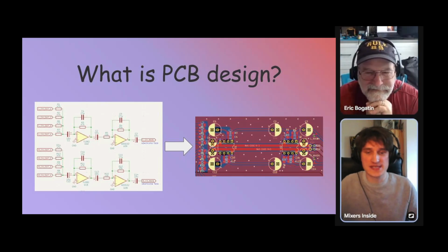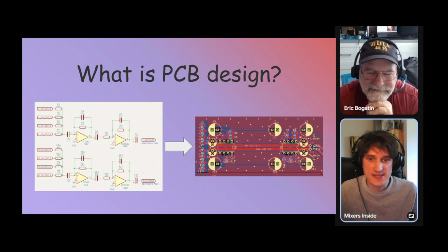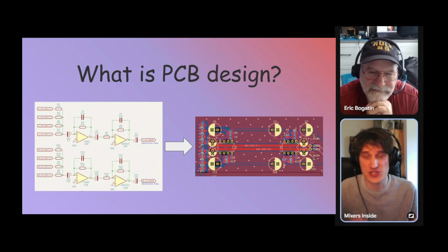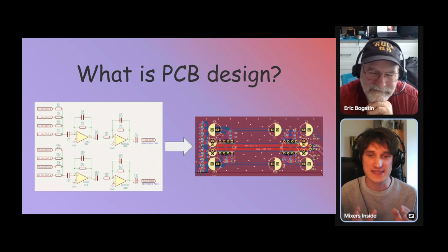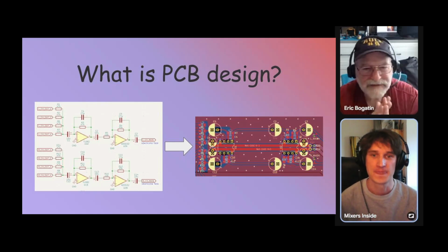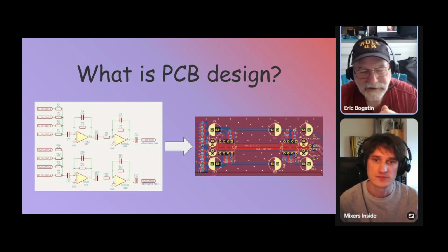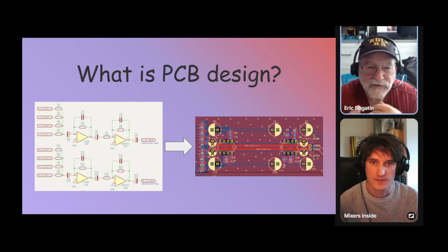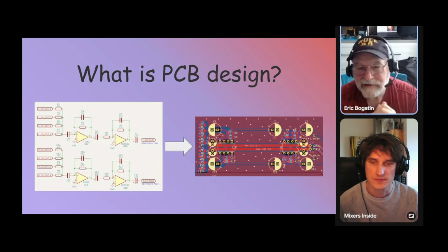Yeah, maybe the best example would be op-amps that have very high performance, and on the datasheets we can see some crazy low THD numbers and crazy specs, but we must be aware that when we lay things out wrong, we wouldn't get the best out of this, yeah? Exactly. And sometimes with op-amps, if it's high gain and high bandwidth, you get feedback from the output to the input through the interconnects that is not in the schematic. It is in the physical interconnects themselves.